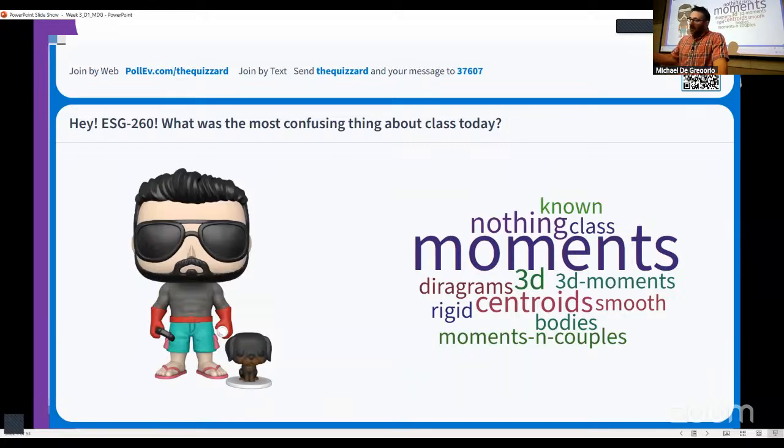Same deal with a triangle. If I were to find the center of the triangle from left to right, assuming that the fat end is towards the right, it's going to skew towards the fat end. Same deal if I go from bottom to top, that starts to move it up. And so what we end up with is, we don't really typically care about the y direction of the centroid at this point, because we're applying it on the surface. We care where it falls on the surface. So that's 2/3 away from the skinny end or 1/3 away from the fat end. And that's because of how that area is distributed. You have more area towards the larger end of the triangle than towards the smaller. Okay.